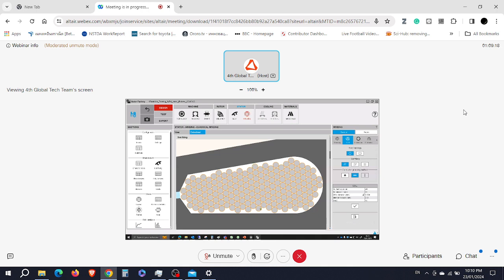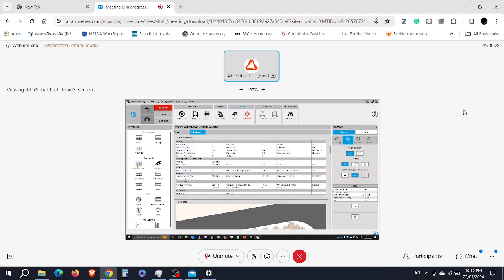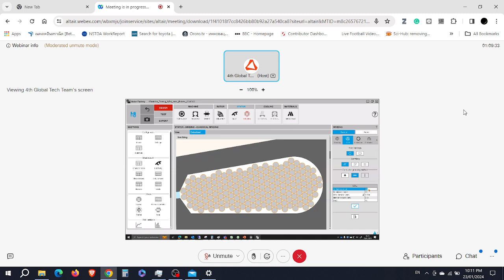It means that your winding is not feasible, and you can check as well the field factor, which is not feasible and realistic. So if you need 8 turns, then you have to play on the number of wires in hand to fill the slot, because here you have a lot of area without any usage.